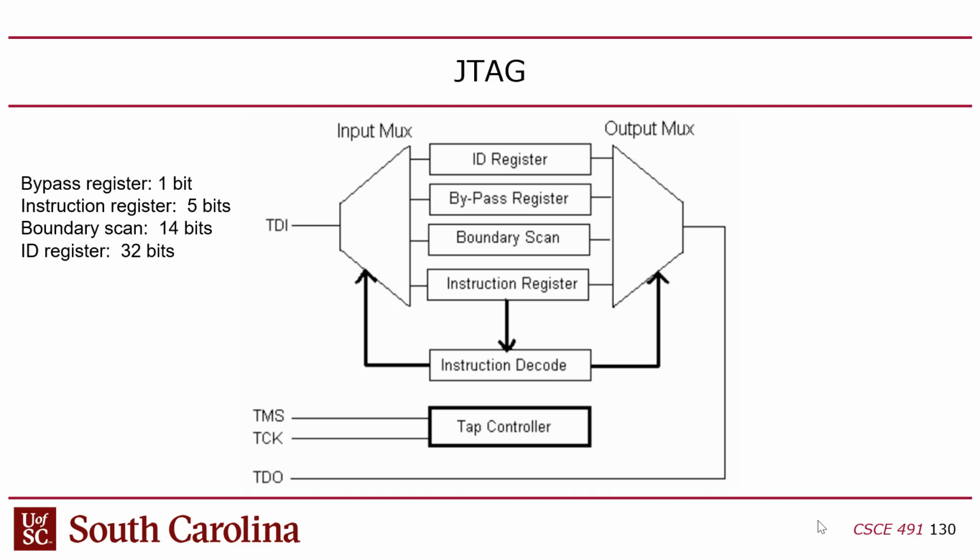It'll give me like an address, like a vendor ID, right? You guys have heard of vendor IDs, like a MAC address, like a hardware address. So if you go inside the Quartus programmer, which you guys use in 3.13, and you hit Probe Bus, it'll actually show you graphically what's on the bus, right? It'll tell you how many chips are there and what their IDs are. You might be like, how's that work? It did that by essentially reading the ID registers of the JTAG chain.